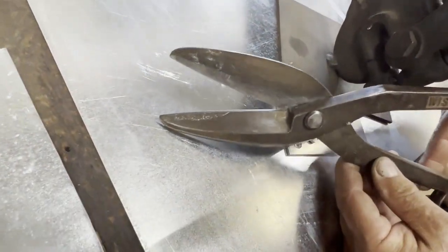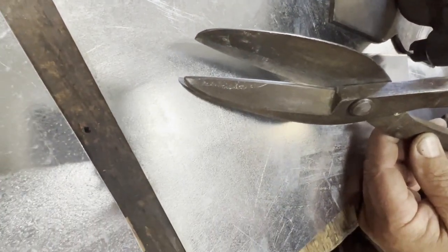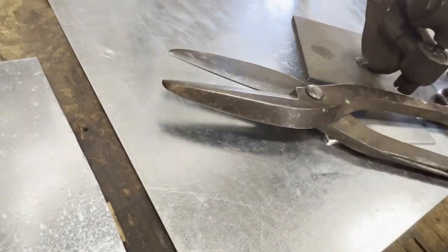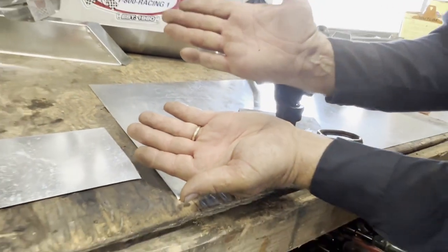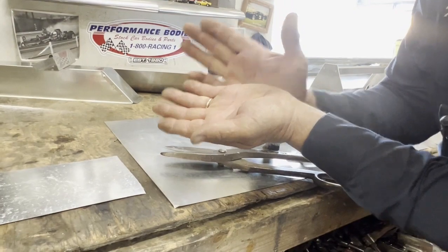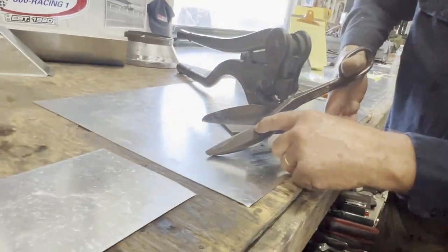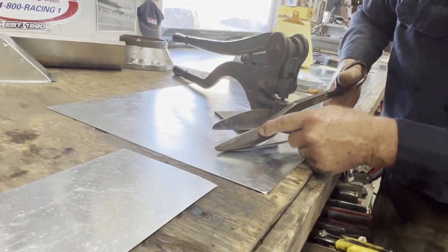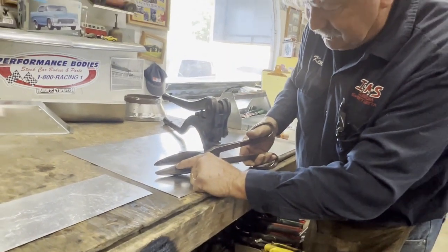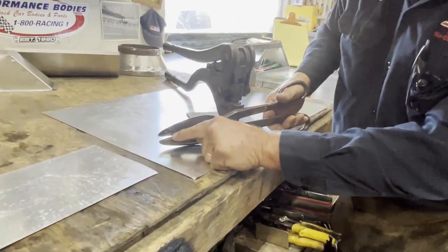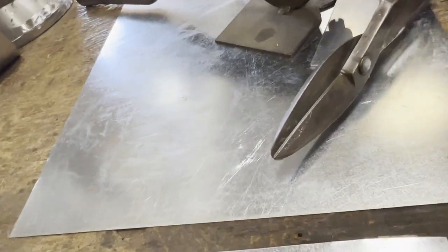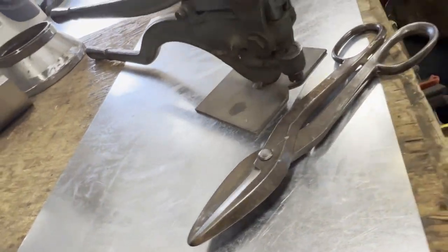Let me turn it this way. I'm going to do that one more time. All right, we ready? So what I want to show you is the differences. The shear blades don't come together this way. The shear blades come together this way, so that as we shear, we're continually focusing our power on a very small place. And the reason we focus that on a very small place is because that gives us leverage over the work. So as an example, let's just say